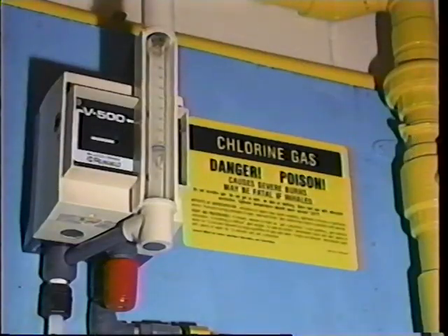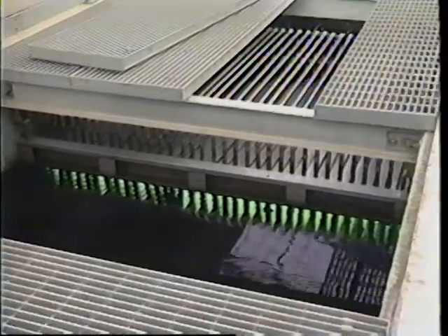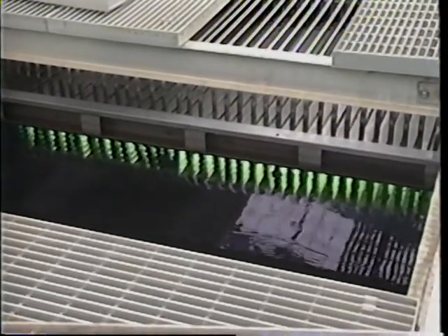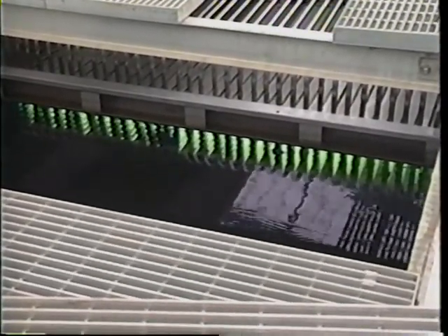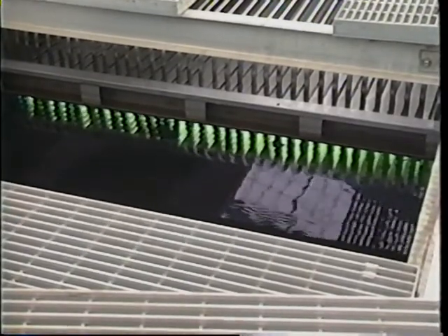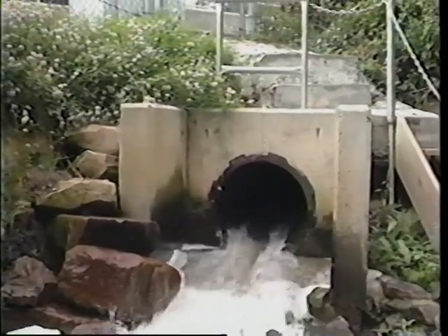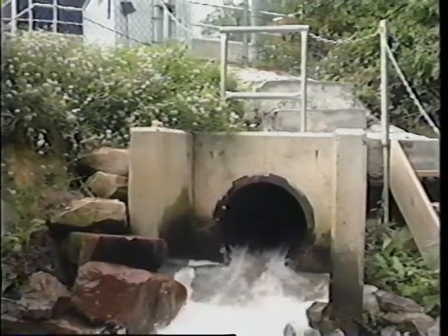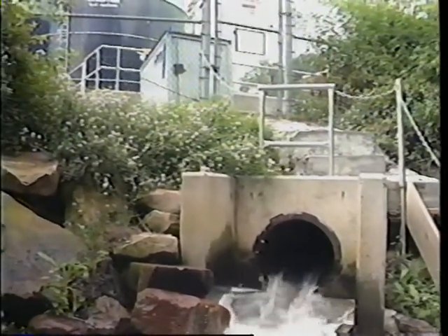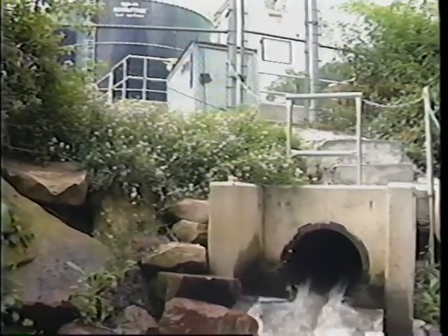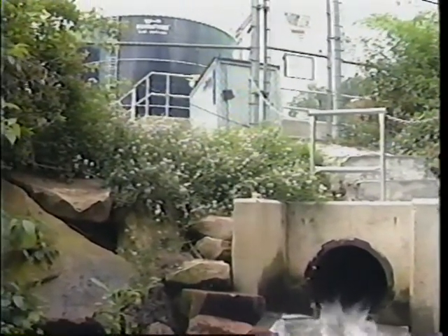Finally, the treated wastewater flows to the disinfection stage. Disinfection kills disease-spreading pathogenic organisms, and this is accomplished through the addition of chlorine, ozone, or ultraviolet light. Only now, after receiving proper treatment and disinfection, can the treated wastewater be released to receiving waters as quality effluent and in compliance with the facility NPDES permit.